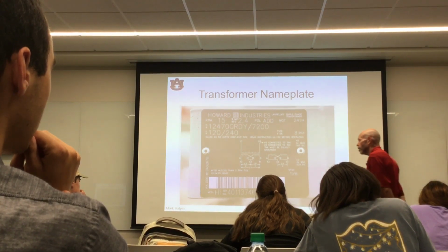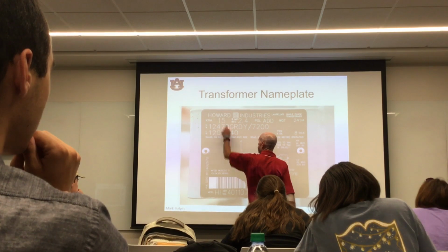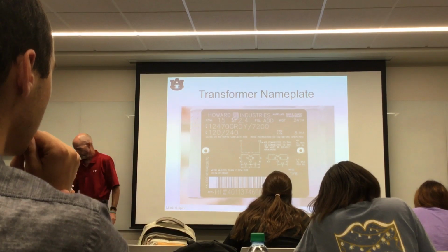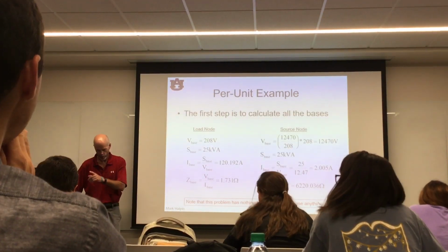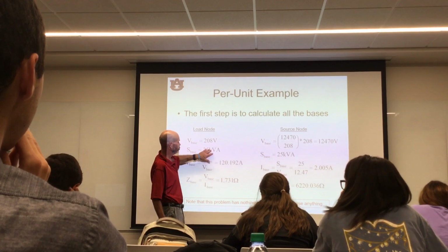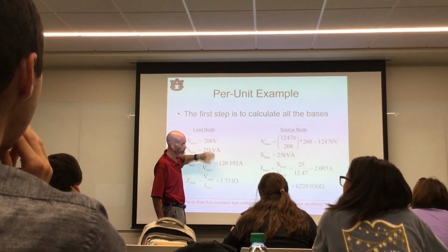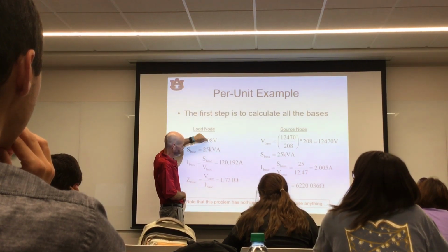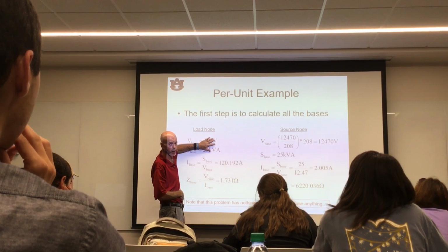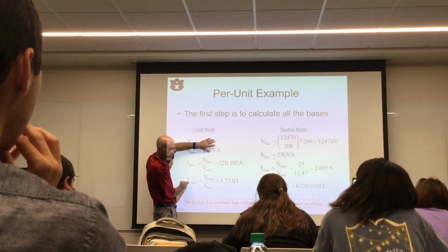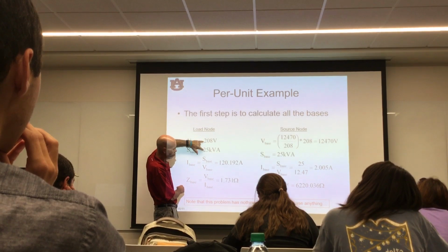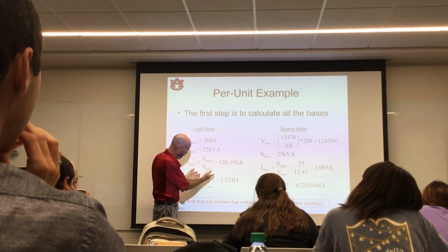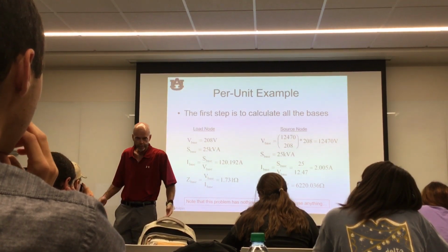2.4% of what? Well, there's the power, there's the voltage. Okay, I'm just pointing to this side. Ignore the fact that this is low voltage. There's the power, there's the voltage. Now that percent imp, that's an impedance. I need that. Once I've got these two, I can calculate that. I gotta make a step or two, but I think I can handle that with a phone calculator.